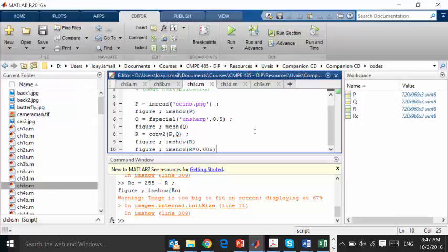It's multiplication and shifting and addition and lots of things. But what is the purpose of doing convolution? Actually, all of the operations that we are doing here, or the matrix that we are creating, are in the spatial mode, in space. Right? Okay? And if I want to apply a certain filter, either to enhance, to blur, to detect edges or whatever, in this spatial mode, I can do it with the filter using the convolution.